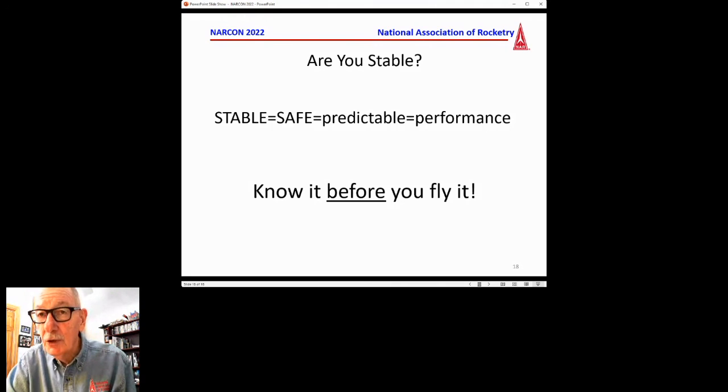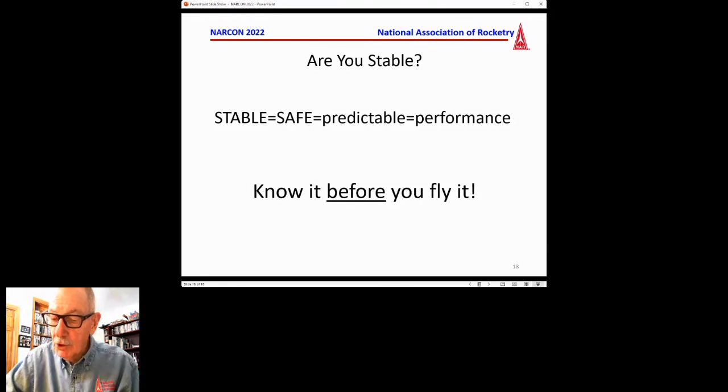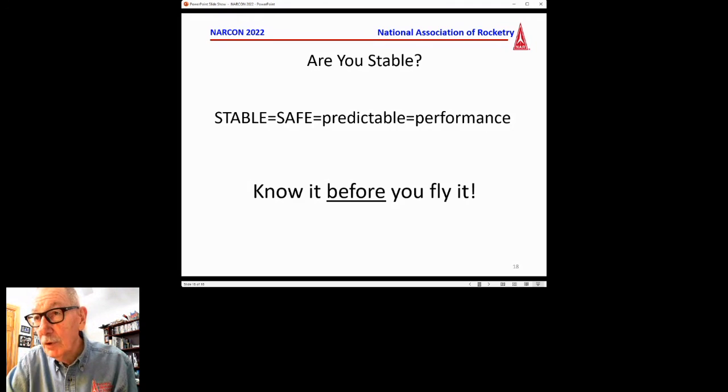However, if there's a discontinuity, like a cone has a discontinuity, because unlike an ogive or a spherical nose cone, it doesn't come in smoothly and tangent to the body tube. If you visualize that when you draw it, there's actually a bump there. That's probably why you see a bump in the Air Force diagram, and I think that's what you may be talking about.